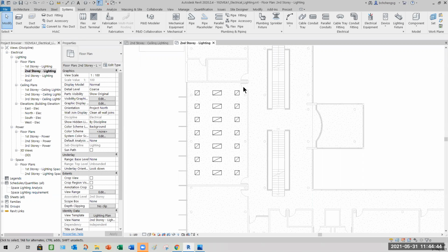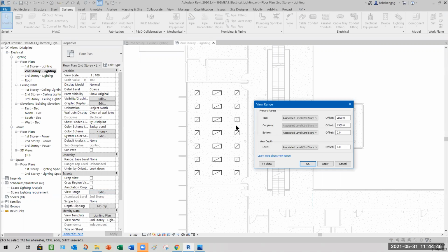So you know what I do? I just change the top. Just now it was 2.3. So sometimes you want to maintain this because in a floor plan, you should see the door opening. Okay, must always think of ways to adjust your view. Make sure it's clear to you and visible to other people.